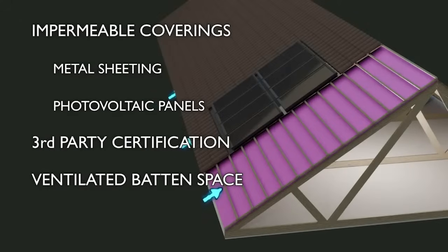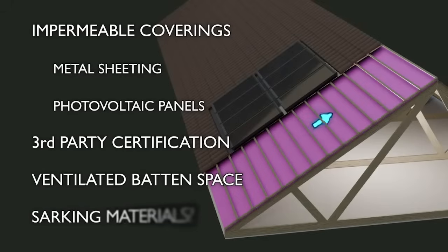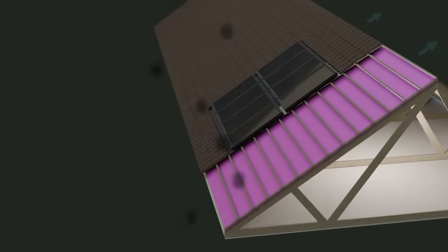In some specific situations, such as where wind loads may be particularly high, or where traditional Scottish slating practice is being used, there may be sarking materials present on the roof. In such cases, it's always a good idea to check what effect the specific sarking type has on the ventilation requirements for the roof, particularly if reduced or no ventilation is proposed.